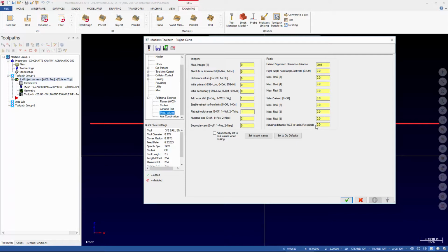So it's not holding that tool point stationary like tool center point control and moving the machine around that tip, the pivot point of the tip of your tool. It's just moving B and C or A and C regardless. So you need to make sure you give it enough room.